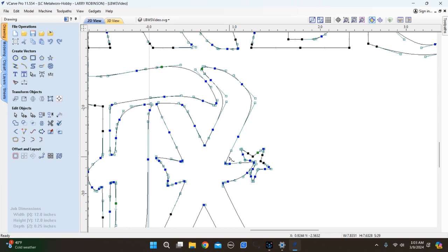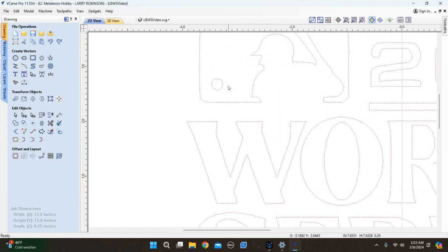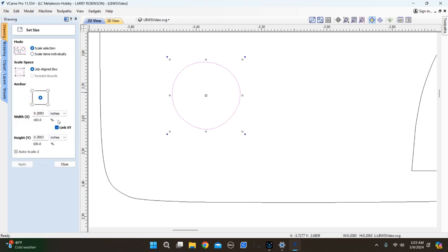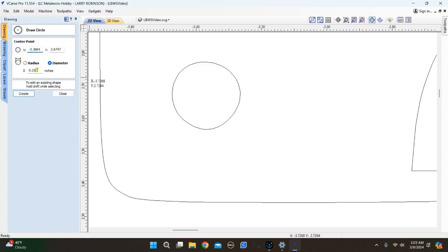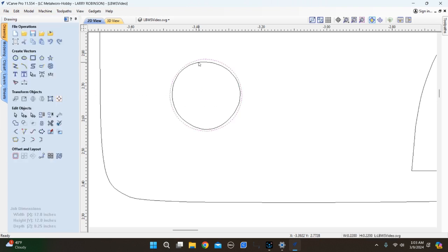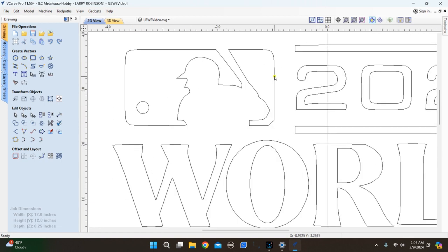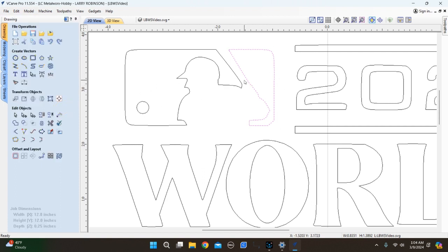And so, like I did earlier, just go in and fix stuff. Just like that little ball, you remember we fixed, so we just checked size. It's less than 0.21. So this might be something in there bigger so we can see it easy. Let's go 0.22. Great, right there in the middle. We've got a good circle there, and then we just click that one, push the delete, and we'll get that fixed. And you can see then the nodes look a little, we're gonna close it to push that in.